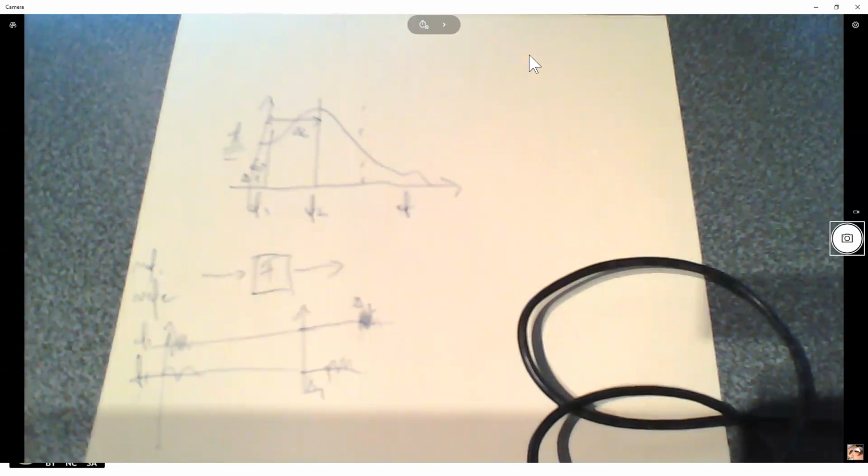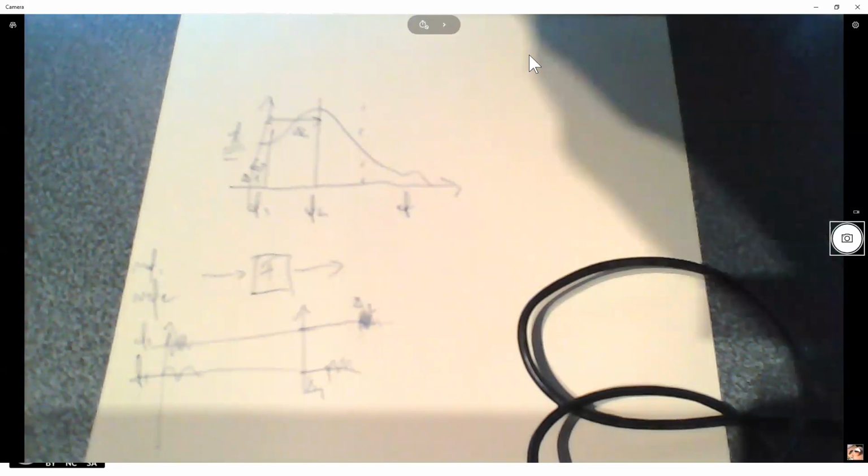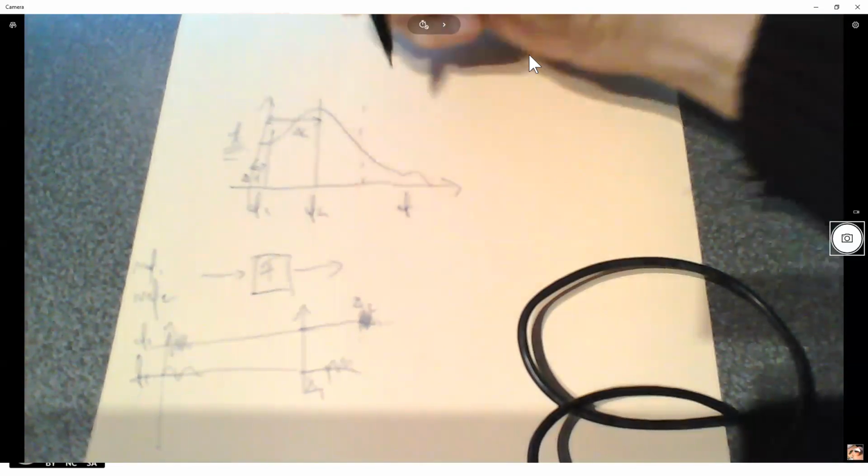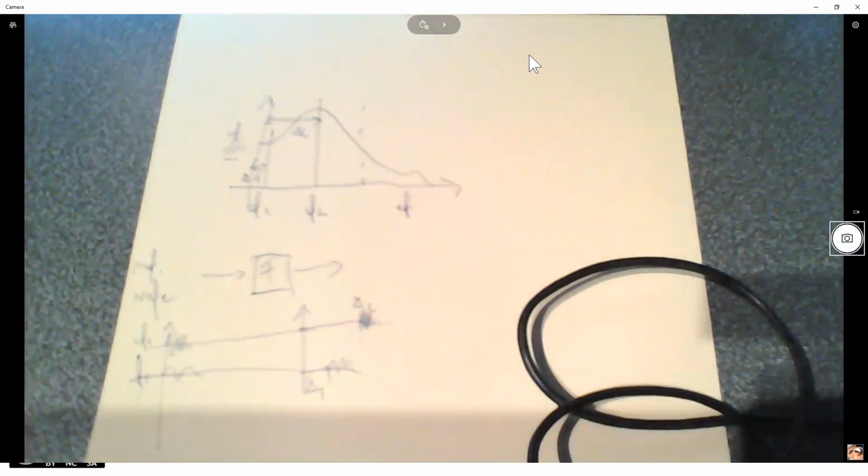If you have a totally digital transmission, then you will design a system with a linear phase response, meaning constant time delay, constant group delay.